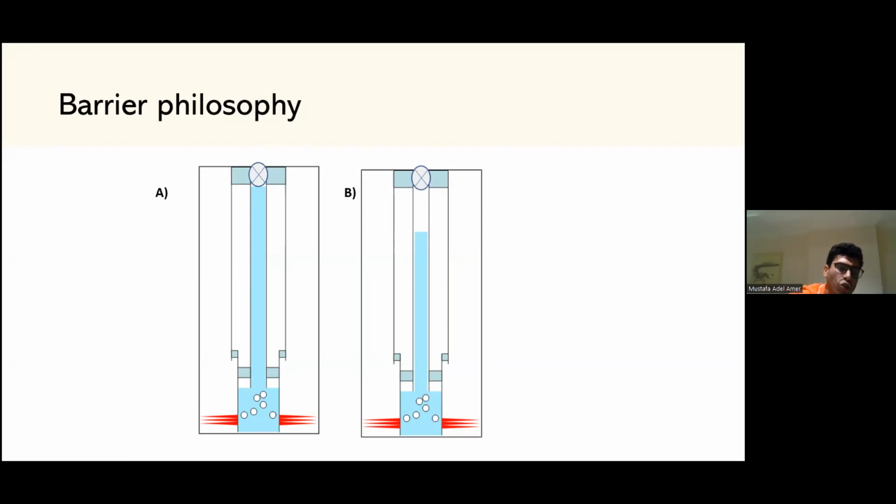So you can't say that the tubing is a primary barrier because its elements intersect with the secondary barrier elements. But here in well B, we can consider that the fluid column is a barrier itself, because all in all, the fluids will not go out of the reservoir by themselves. So in this case, the oil fluid column in the reservoir and the well is considered the primary barrier, and then we can take the packer, the lower master valve, and the tubing as the secondary barrier.